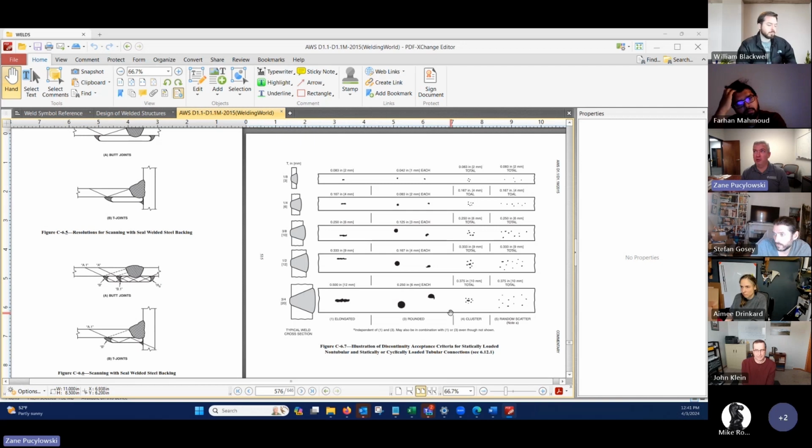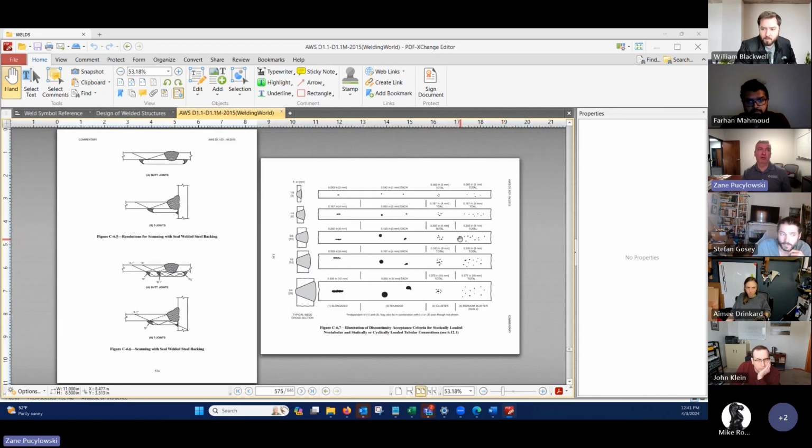And this is why I highly encourage, and I do all design of welds with base metal material strength only. I don't give any credit for the stronger filler. And this is why I use really high factors of safety, because I know I'm not going to get perfection in the field. I'm probably not going to have it inspected. They're probably not going to write a procedure, right? So cover yourself and the people that are using the things that you're designing. Make sense? All right, that's all I got.